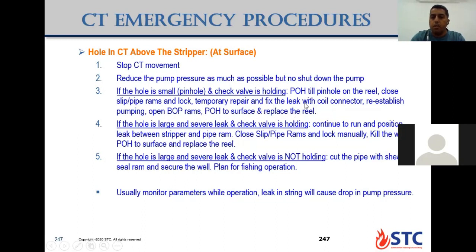So you need to replace and check the reel. Maybe you have another pinhole, or in some area you have wear in the reel or the coil tubing in the reel. So you need to make a full replacement of the reel with a new one.